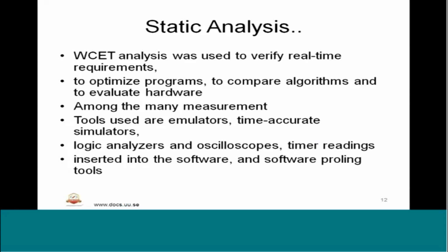Additionally, for timing requirements, memory requirements and all that, we use logic analyzers, oscilloscopes and any support tools such as emulators, time accurate simulators, etc. Also there is another aspect of static analysis that can be done with the help of a test hook or the test code that will be inserted into the software, and there are software profiling tools which will help in terms of analyzing the call stack, stack memory, stack analysis or stack overflow, which we will study today. All this will be done with the help of the inserted code. So that is also a part of static analysis.